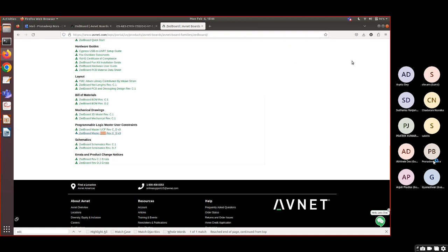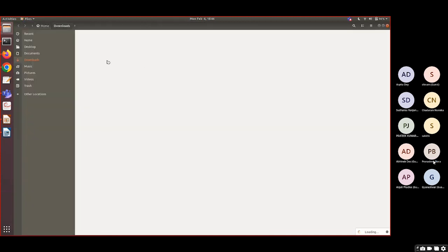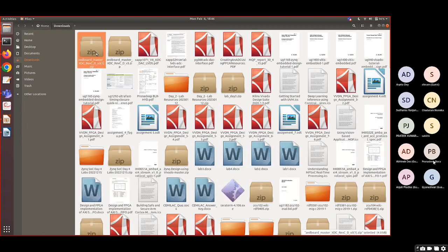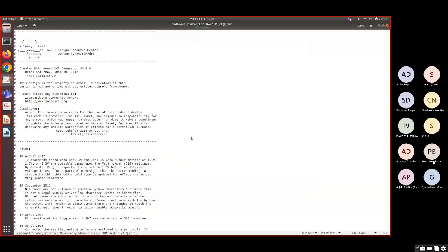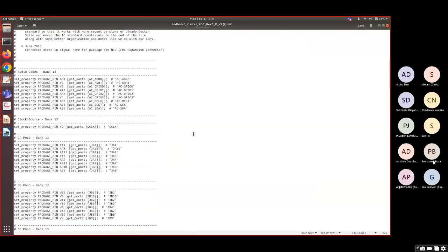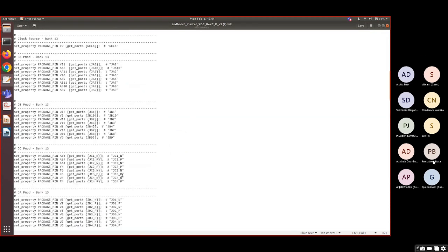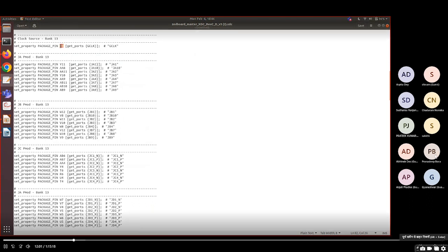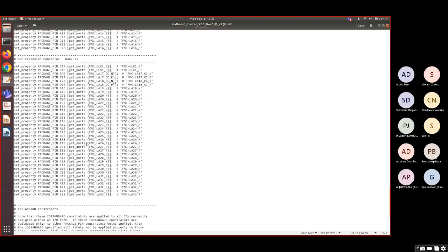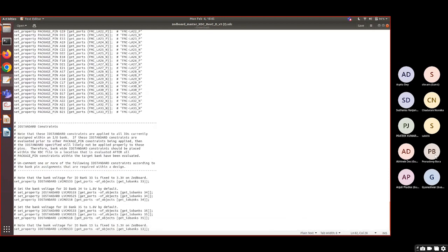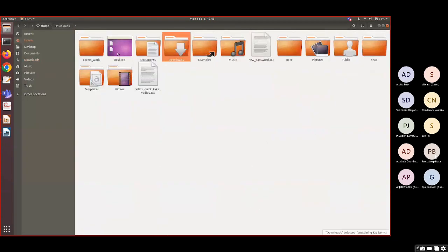Once you have downloaded it, I'll extract it. You can extract it here. Yeah, this is my Master XDC file. So what should the tool know? The tool should know the pin connection, right? What is the pin number? For the clock, I know this is the Y9 pin, so the package pin is Y9, right? This pin number I should know, and from there I will be making the XDC file. Two things are required: the package pin and the IO standard. They have defined the IO standard in one go, but the preferred way is this. So I have provided you.